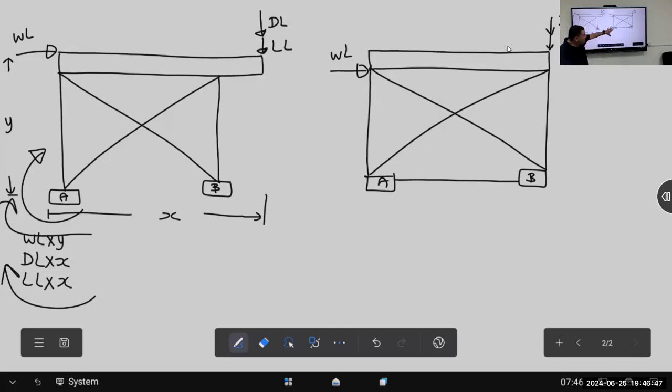And if I do it this way now, what will happen here? More stability or not? More stability. I tighten it, I make it more rigid. So what will happen for foundation B? Foundation B would be overturning. Where is the point of overturning? This point. If there is uplift here, the whole system will overturn about this corner.